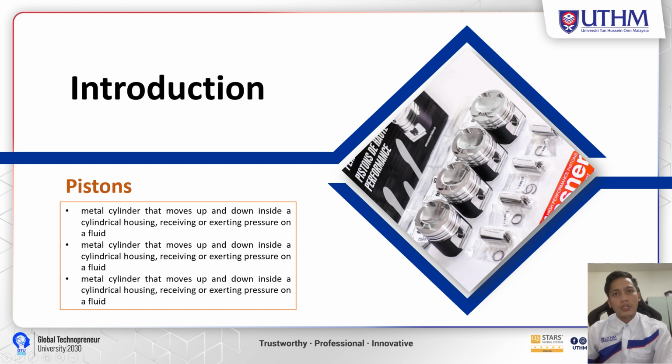Pistons are applied in many machines to transform one type of energy to another or to move fluids such as air, water, or energy from one location to another. Pistons are present in the engine, brake system, water pump, and air conditioner of automobiles. Pistons are often manufactured of low carbon steel or aluminium alloy. High heat, inertial abrasion, and friction are all applied to the piston. The effects of differential thermal expansion between the piston and cylinder walls are minimized by carbon steel. The aluminium weight advantage over cast iron is offset by the necessity for larger portions for strength. For this project, we focus on aluminium alloy pistons.